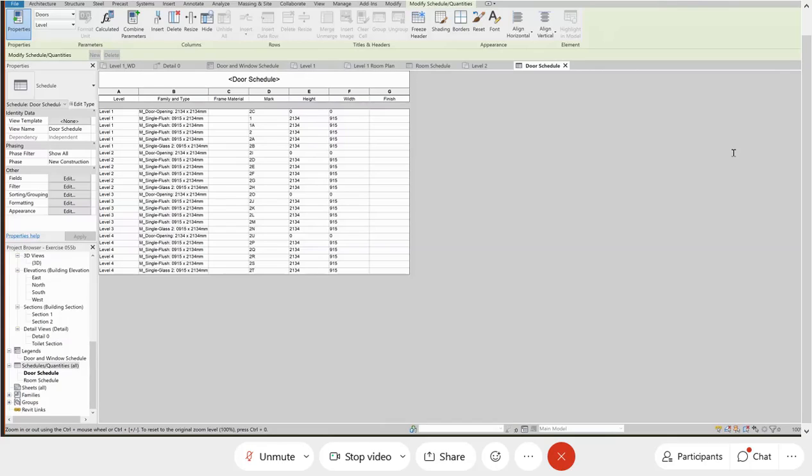Is per person space fixed to 10 square meters? Not necessarily 10, it depends on the function of your space. You can refer to the Metric Handbook or Neufert's Architects' Data. Usually they give you some standards to calculate the occupancy. Just now I did a quick one, that's why I put 10 for all the spaces. But usually different spaces have different occupancy loads.